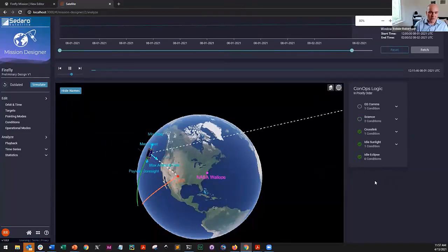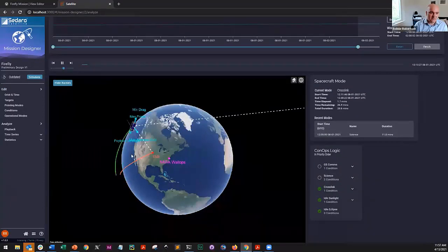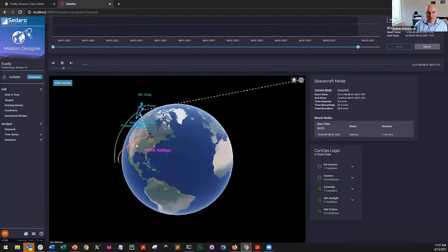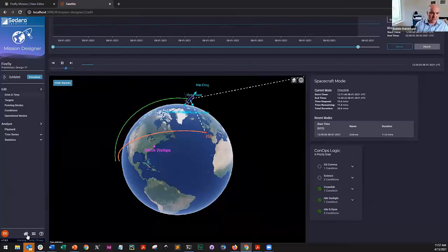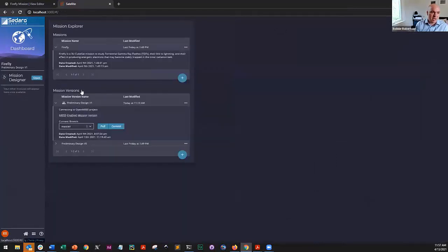So right now we're visualizing the flight dynamics of our satellite, and seeing that we're still in that polar orbit. We haven't re-simulated with the updated orbit data. And you can see why we would have less communications access, because our inclination has more offset from our crosslink satellite, the ISS, and we're just not going to have as frequent or as close passes over our lower latitude ground station.